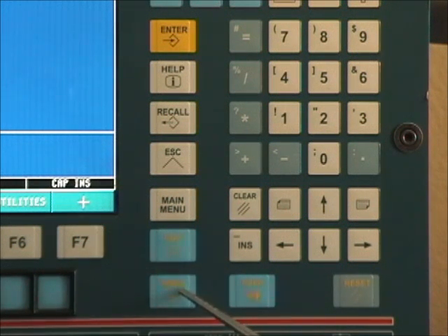In simulation mode, it pulls the editing program and puts it into simulation mode. If you're in execute mode and you wish to edit the program, press edit and it will pull up the existing active program that is being executed. Prior to using these keys, remember to press feed hold or reset.